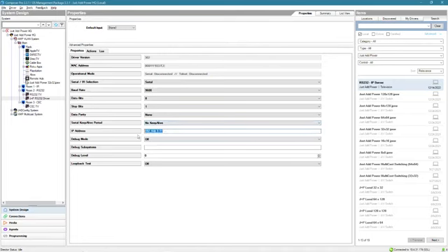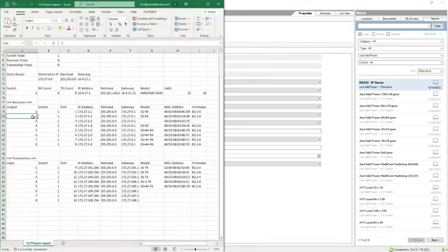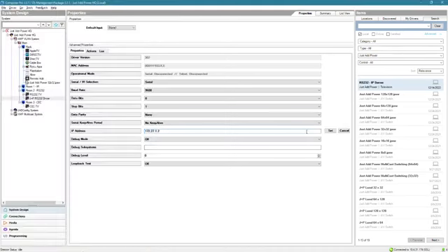And then the last thing we're doing is setting the IP address to the IP of the Just Add Power receiver behind the television. If you don't remember what that is, we go back to our report file. We remember that this is output number 2 in our system. So we're grabbing the IP address for output 2, putting it right there, and setting it. You're not going to see operational mode change other than a very brief message here. So we do have our serial connected. It's doing its thing. And if you're looking at the TV, it'll actually reboot the television in that setting. It's going to apply the serial settings to the Just Add Power device as well.